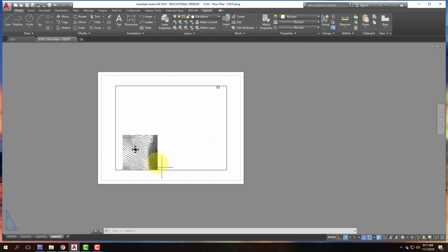And inside of that sheet of paper, you have what's called a viewport that gives us access to our drawing. These viewports can work independently of each other. We can have multiple viewports on a single page. And we're going to work to set those up. But before we actually get started setting up the viewports, we need to set up the page in the first place. So the default page size isn't necessarily what we ultimately want as our page size.